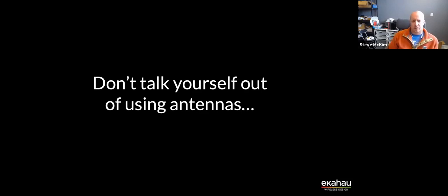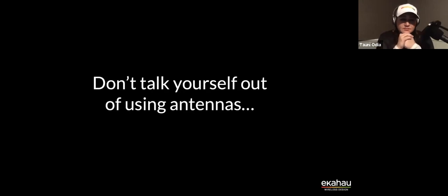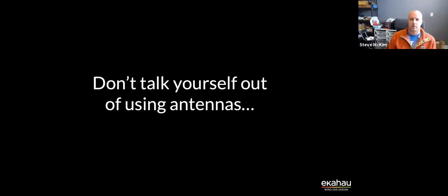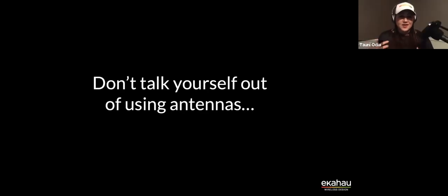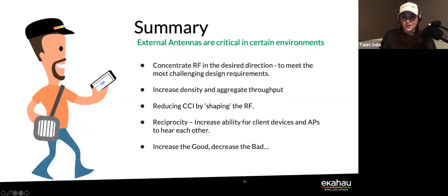I think one thing to remember is not all antennas are created equal, regardless of what the spec sheet might say. There are manufacturing tolerances or manufacturing variations and things like that. I think validation, or at least testing, might be more important with an external antenna. That would be my one thing to remember. Maybe we could do a follow-up on validation of external antenna networks, and what you do if the patterns don't match what your predictive was. Stu, maybe that's something we can focus on.